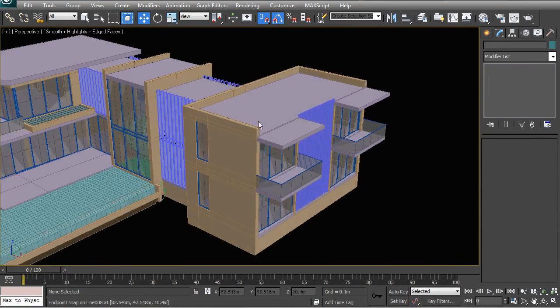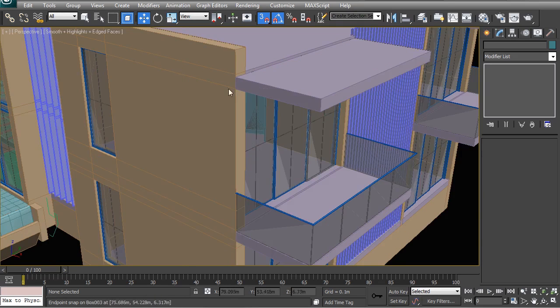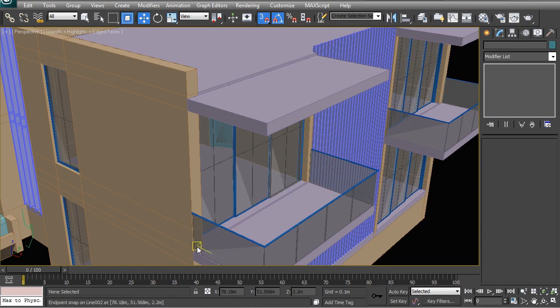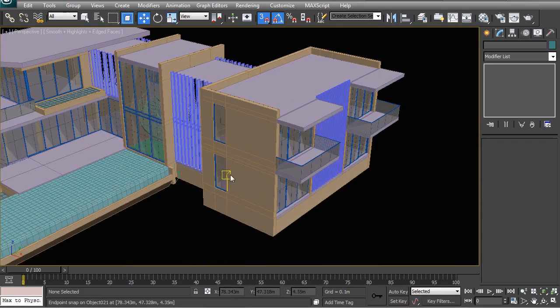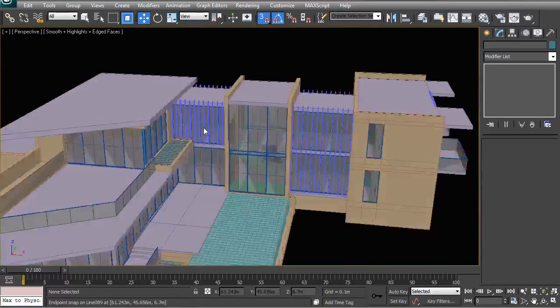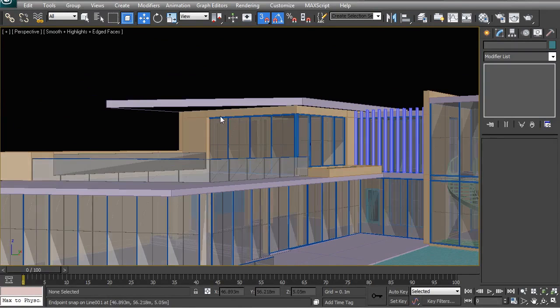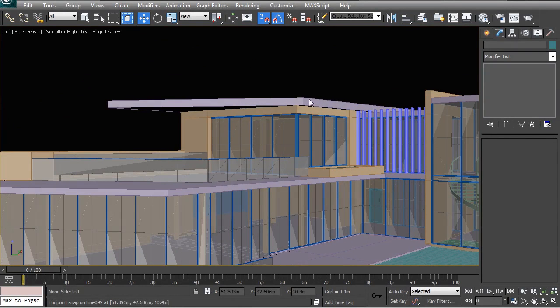Now, in the real world, this would have to be treated with most likely a small parapet, or at least the drainage would have to be worked out on this, so that you would want to get all of your drainage from these portions to drain back into a safe drain and then down within a drain pipe somewhere. You don't really want any water dripping off these edges, otherwise it will make a whole big mess underneath on the balconies below. Anyway, let's move over to the last roof, which is the one sitting above the master suite.